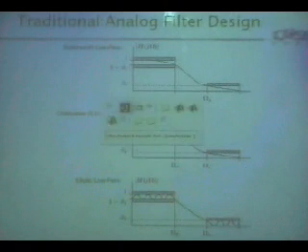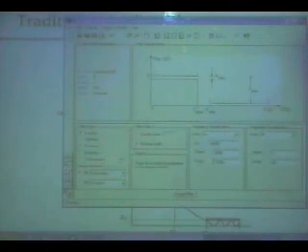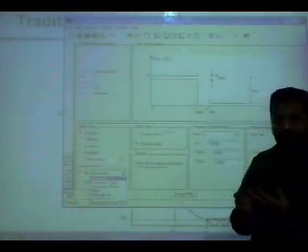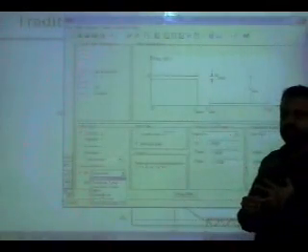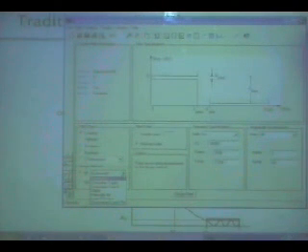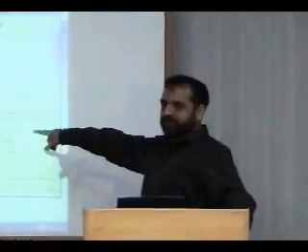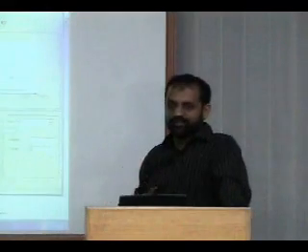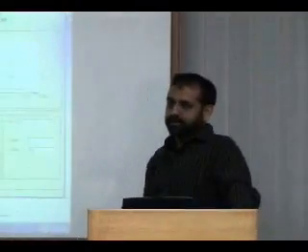If I go back to MATLAB, once you say IIR, MATLAB will give you more ways, but it says Butterworth, Chebyshev type 1, Chebyshev type 2, elliptic, and then there are a few other methods, but this book covers these three methods. The important thing is the differences. Let's first ask MATLAB to design a Butterworth filter, a smooth H of e to the j omega, for these specifications.